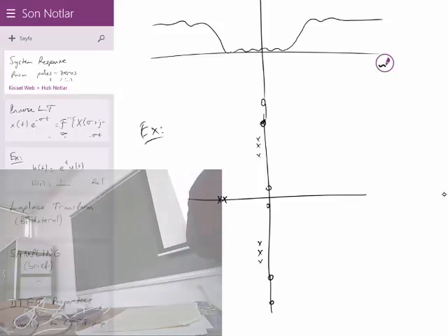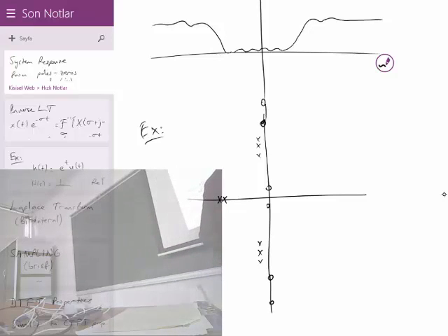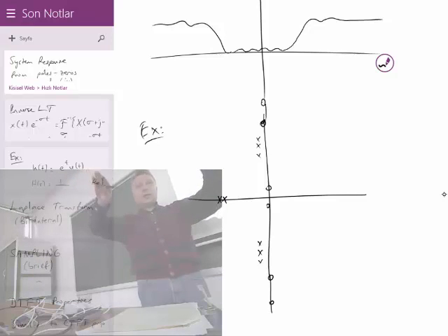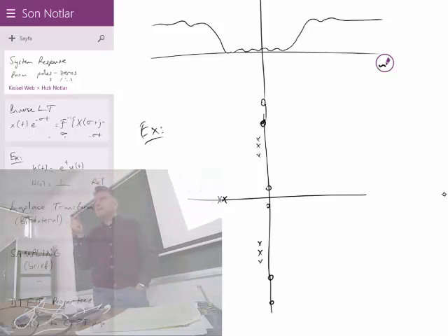They are the frequencies around here where the frequencies are nearer to these poles. They increase. And then towards here they become this time nearer to some zeros. In fact they touch the zeros, so they go down. So the shape is down, then increase, and going down again. So that's a bandpass filter. So is it sharp enough or whatever? I don't know. But this is the idea.